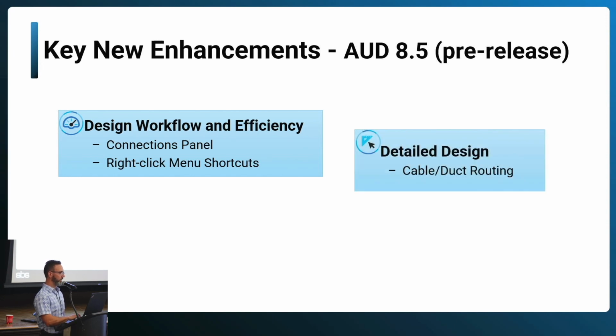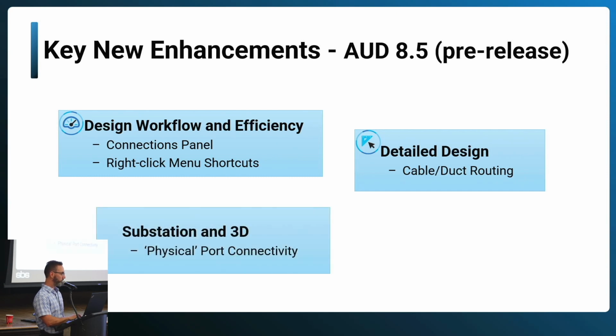Some command enhancements that allow you to do some automated cable or duct routing. And then for a substation in 3D, the ability to establish physical ports as opposed to logical ports. And this is kind of a new concept we've introduced, and it's to deal with being able to maintain both a high-level network connectivity model, but also deal with the fact that, well, in a physical layout, there might be some details that need to be physically modeled that would otherwise sort of complicate the electrical model.